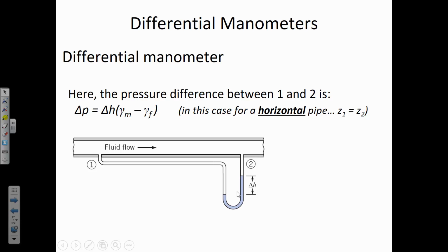Pipe friction. Yeah, so remember the no-slip condition? That diagram we looked at earlier in class, where we know that as water or any fluid flows adjacent to a stationary surface, that interaction and the shear stress that's applied is going to reduce the energy that's available. So there's less pressure at 2 simply because as the fluid flows, energy is lost due to pipe friction. All right.